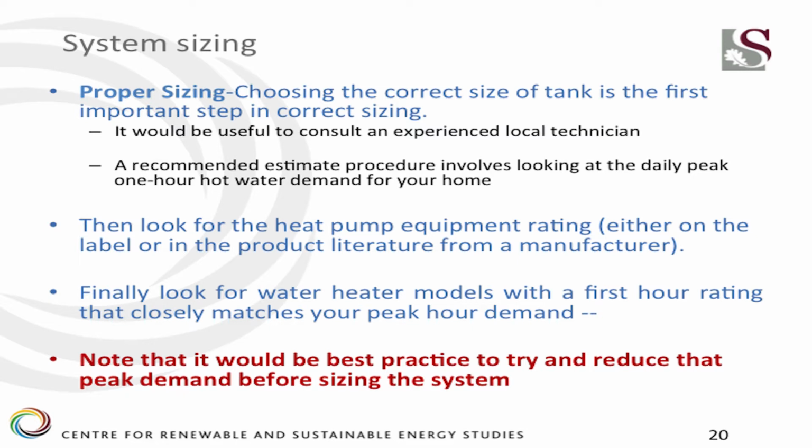Sizing. Choosing the correct size of tank is the first important step. Again, using an experienced service provider is recommended. The equipment is normally standard equipment. You look at the label or the product on the web, the literature from the product manufacturer. And finally, look at water heater models with the first hour rating that closely matches peak demand.